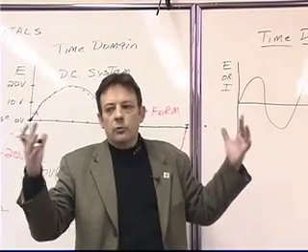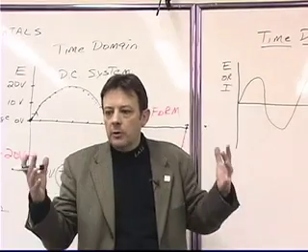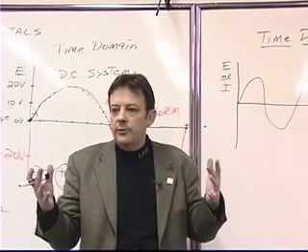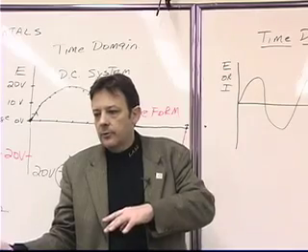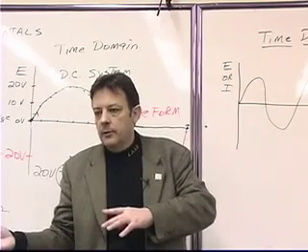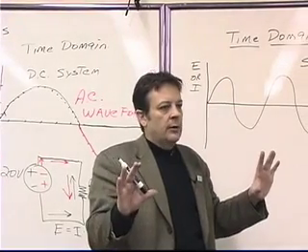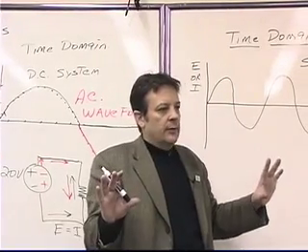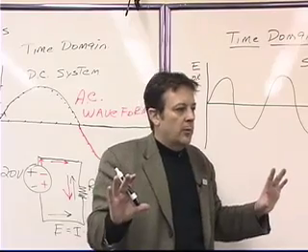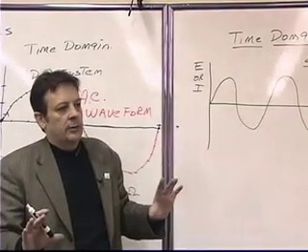And if you tried to run interconnected power grids at different frequencies, the system would crash. The system would not run smoothly. Okay, so everybody has to decide on a frequency, decide that they can live with it, and then build all of their equipment so that it's going to run at that frequency.